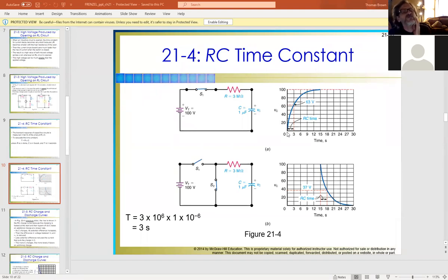In the future, we'll be looking at that. Oftentimes in electronics, for circuits such as filters and whatnot, we do look at 5 time constants. 1 time constant to get to the 63%, or to begin the effective charge, if you will. But notice it's 5 time constants to be fully charged to the wave shape that we're going for, or the charge that we're going for.